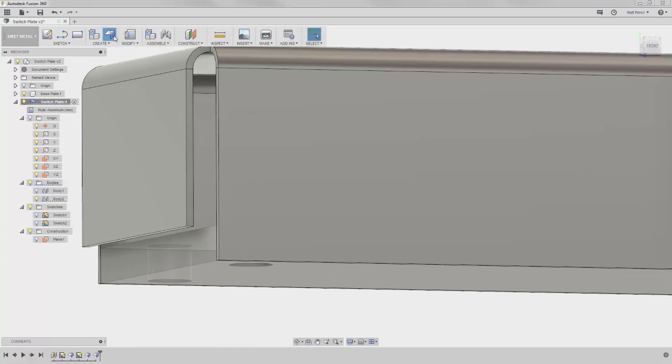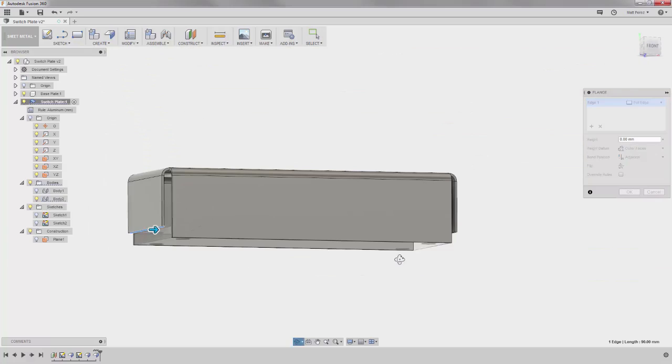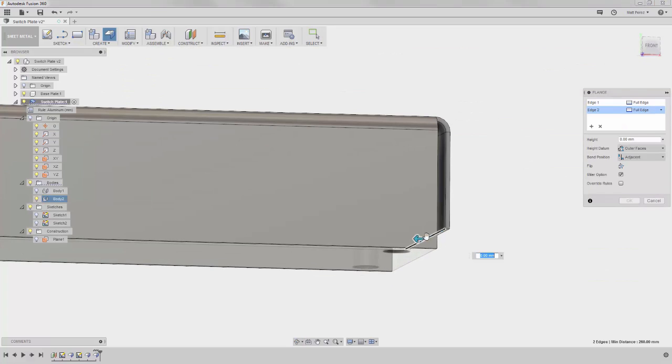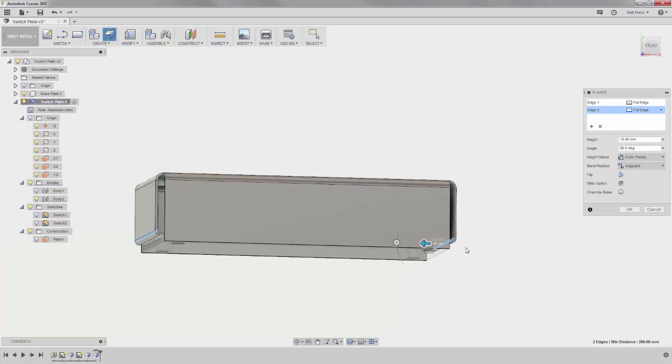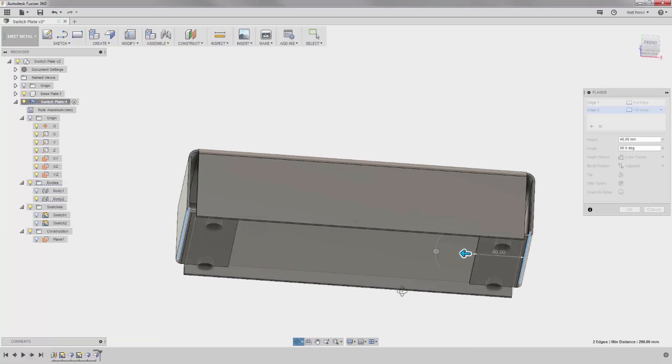Now we can begin creating the flanges that will go on top of the base plate by selecting the lower inside edges of the flanges we just placed. As soon as the second edge is selected, we can begin pulling the new flange in, and you will see that both are pulling away from the selected edge in the same manner, even though that means they are developing toward one another.